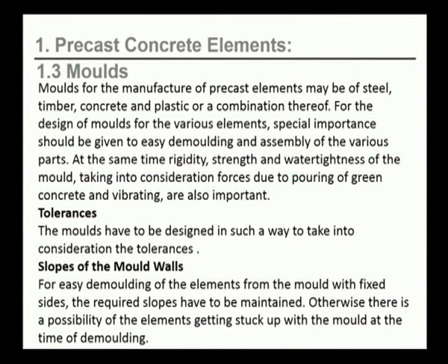At the same time, rigidity, strength and water tightness of the mold is an important part, taking into consideration the forces which are exerted on the mold due to the pouring of green concrete and vibration. Now, tolerances. The molds have to be designed in such a way taking into consideration suitable tolerances.